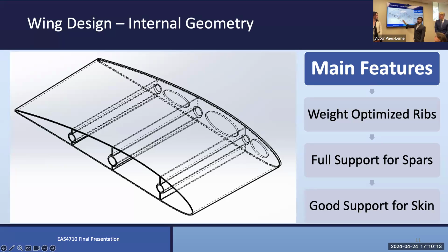This one was very useful for our layout process. I think in either the midterm presentation or this one, in the manufacturing slides, we were able to have that hanging down like a coat hanger. So it's ultimately not purely for calculating normal stress from bending, it's also for manufacturing. The trailing edge one and the leading edge one were the ones the actual spars were in. The middle one was just for electronics, and we also use them for shear joints to glue it.